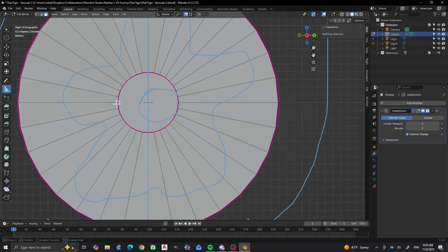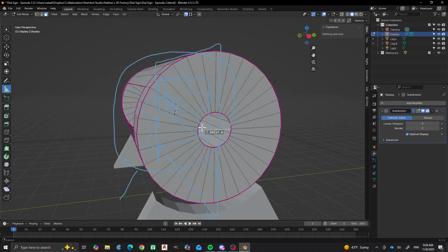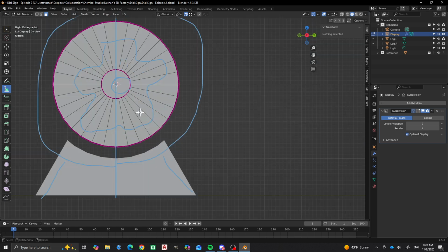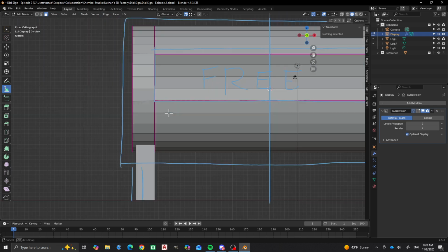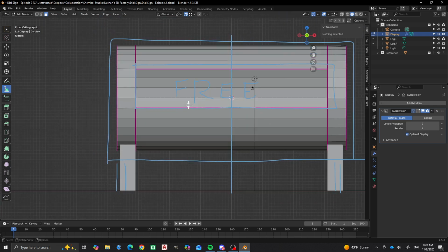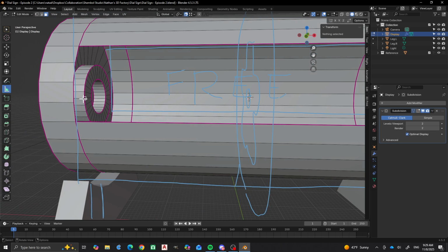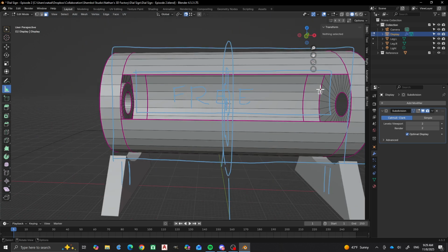And then on this, 7.8 is what I'm seeing. Let's make sure that we actually have this measuring from one vertex to the other on the same plane, which it looks like we do. So now that we have that, we're going to say a 28 millimeter, so 14 millimeter radius, I should say. And then as far as the width, I have to get from here all the way to somewhere over here, right?